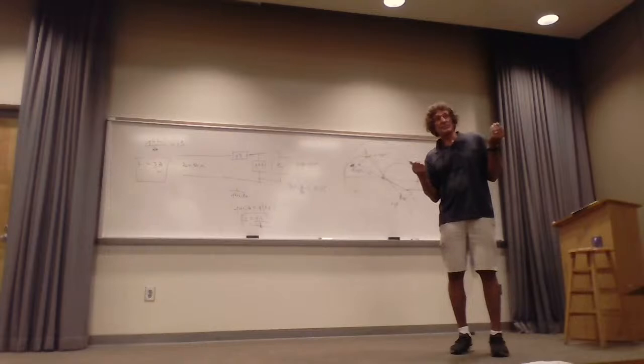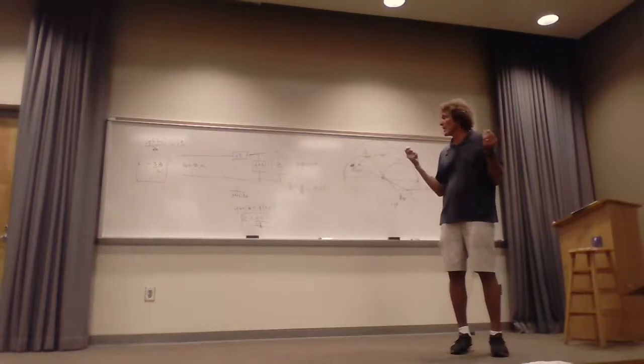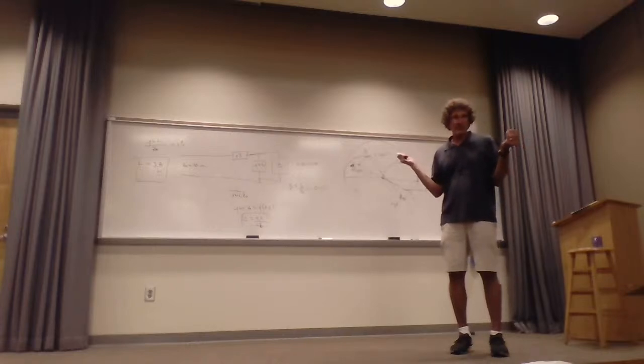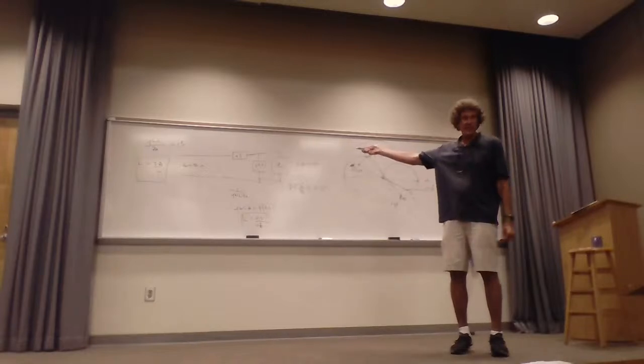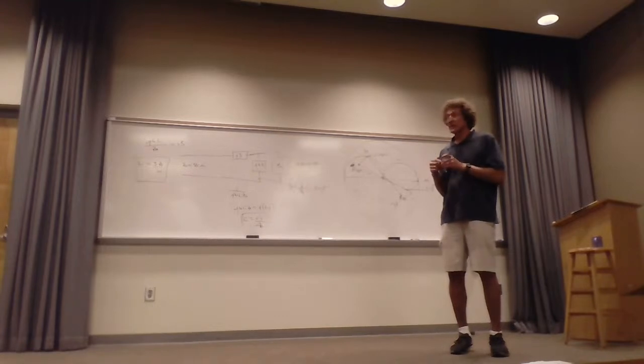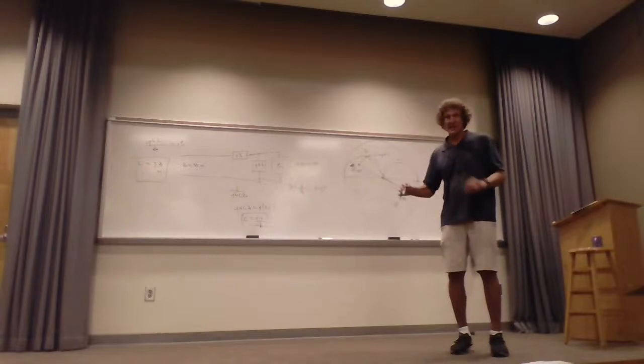When the normalized impedance is inside the one circle, or the load's magnitude is greater than Z naught, I have to put something in parallel first, then in series. See how it was parallel first, then the series? Well, if the load impedance magnitude is less than the characteristic impedance, then you add an impedance first, then admittance.